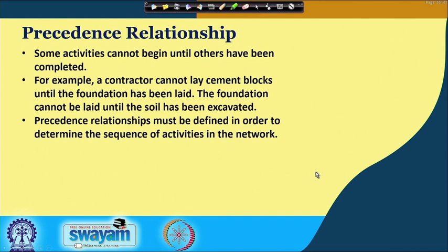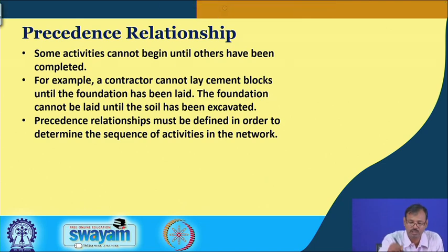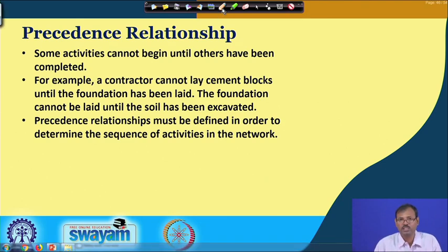So, this is another type of representation of the activities in a different form. This precedence relationship establishment, successors relationship establishment, is the essential requirement of the construction of the network. This is very important and the user must be very careful about this assigning. As we observe in drilling and blasting, drilling is always the predecessor of the blasting.